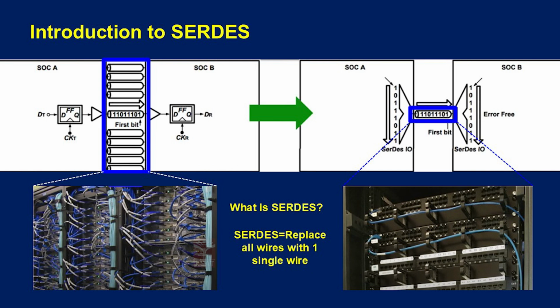So basically you are muxing. I'm talking about mux and demux, right. You are muxing all this data. Mux means getting all the data in a time multiplexed manner, taking the lower speed or wider dimension data in the time domain, clubbing everything together and then putting it in the channel.